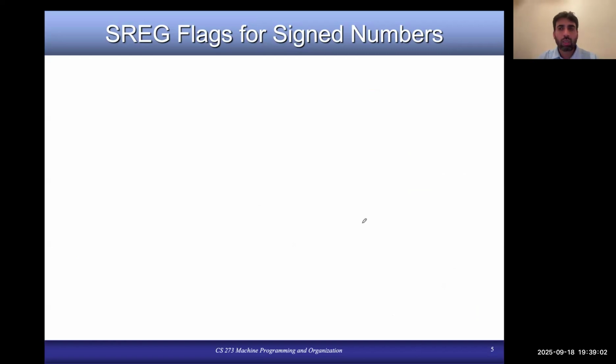No? Okay. So last time, in the last lecture and the lecture before that, we talked about the status register, and we also talked about how the branch instructions which we have covered until now basically check your carry flag or the zero flag. For example, when you say branch if same or higher, or branch if lower, or branch equal or not equal, you are either checking the zero flag or the carry flag, right?